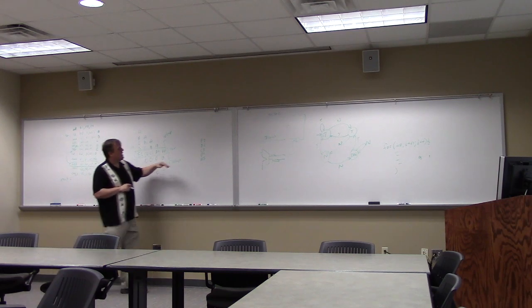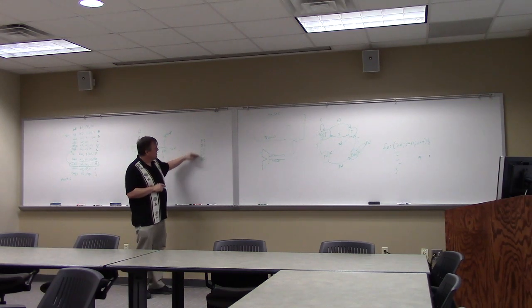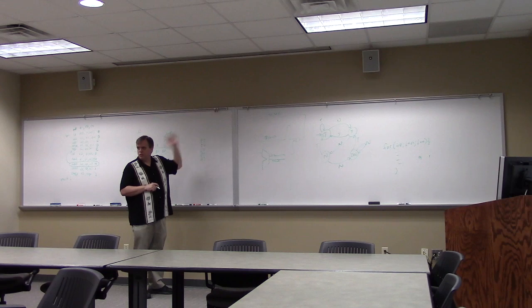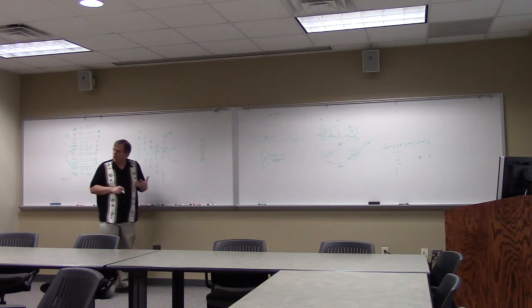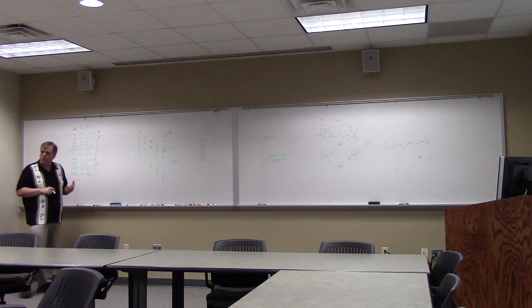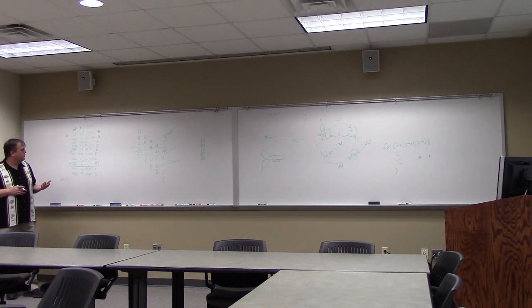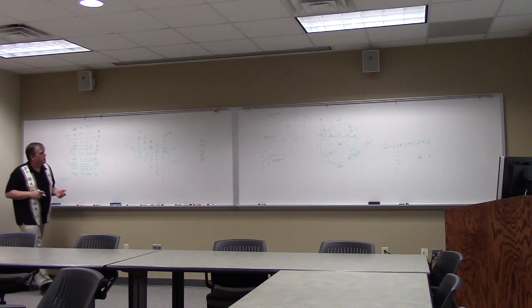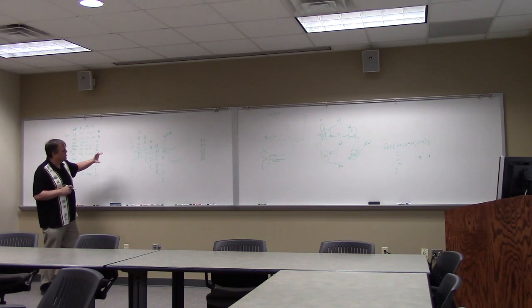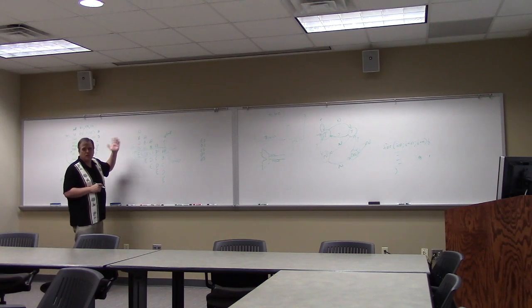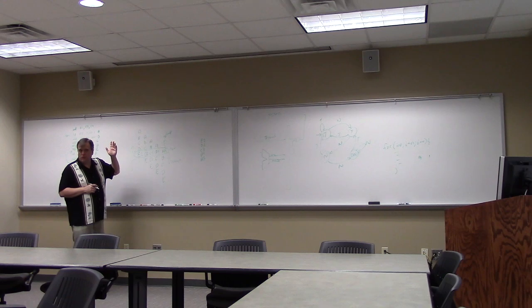If E decides not to branch, then these commands won't happen because it'll jump out. This would be one of those jump and leave type of situations. So I could put a jump and leave on there, but as long as I put the memory commits for my stages, and I don't let the other ones in between commit before then, I'm going to be safe.